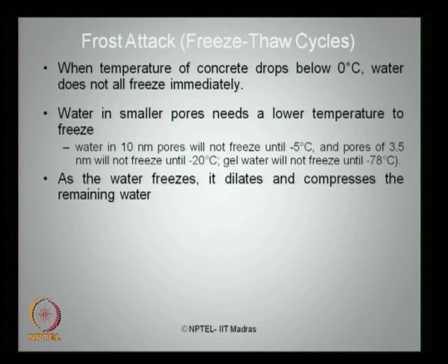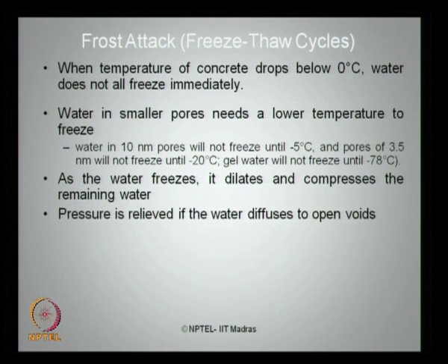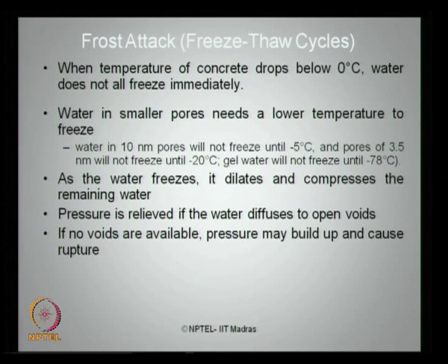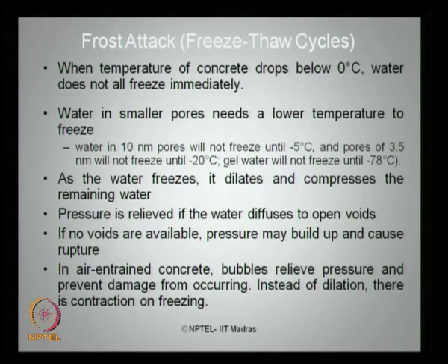As the water freezes, it dilates and compresses the remaining water. Pressure is relieved if the water diffuses to open voids. If voids are not available, then pressure may build up and it causes rupture in concrete. If air enters the concrete, bubbles relieve the pressure and prevent damage from occurring. Instead of dilation, there is contraction on freezing.